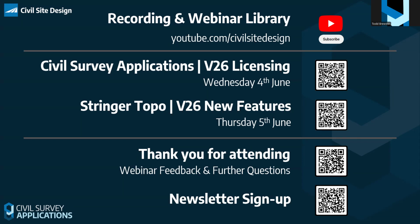You're probably already most of the way there. Once you get the new version, you can make a model builder model and then run IFC export, and it'll throw it out into an IFC file built from whatever the subgrade conditions are on the template that's applied. Probably the key thing I didn't really highlight, and I'm going to say it now, is that on the sections I used for Islet Street and roads 1, 2, and 3, I actually added a subgrade condition to every piece in my model. Even if you don't want there to be any depth, you want it to be zero depth, but you want it to be part of the IFC export, you can put a zero depth layer inside your subgrade definition, and then it would go across into the IFC. If you have just a code in your template that has no subgrade conditions at all, then it won't go through into the IFC or into the subgrade model manager in CSD.